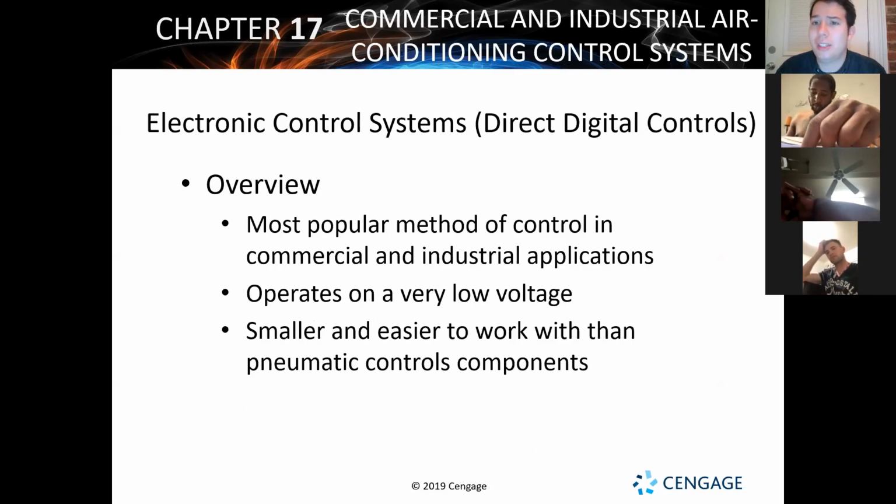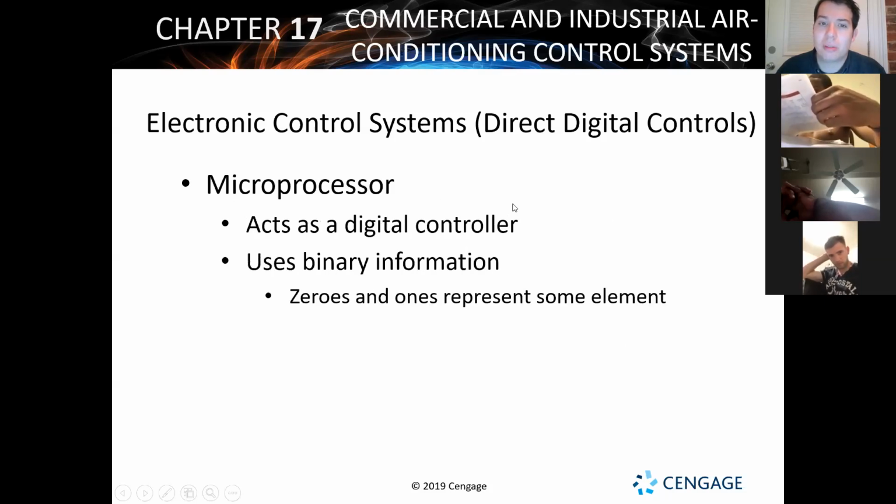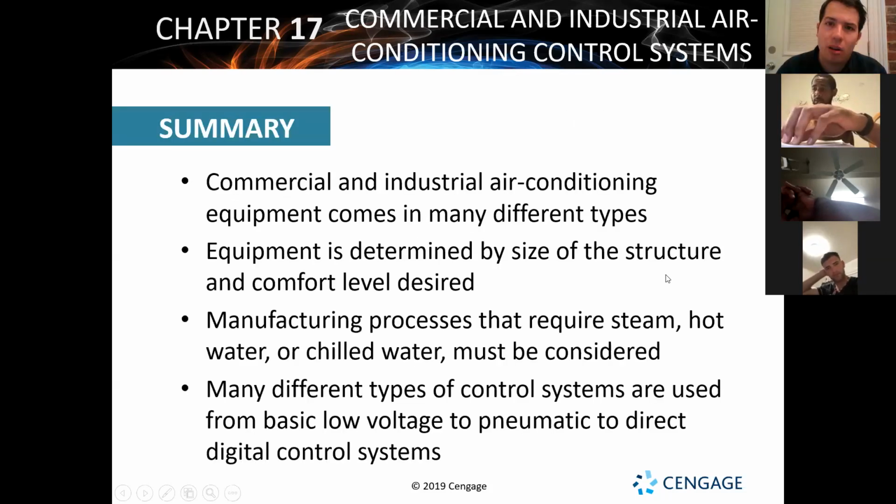Electronic controls, or DDCs, direct digital controls, these are the ones I was talking about where it's going to take up like an entire room sometimes, depending on how sophisticated it is. These are the ones where you can also hook up a laptop. If it's a DDC control system from the early 2000s versus 2020, it's iffy whether or not you're going to be able to hook up a laptop to it. Nowadays, pretty much always, you can hook up some sort of computer with it. And with that computer, it's going to be reading the information from this microprocessor, the actual computer part of everything. All right, cool.